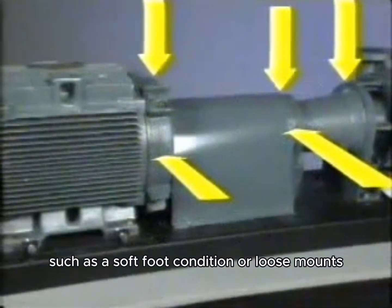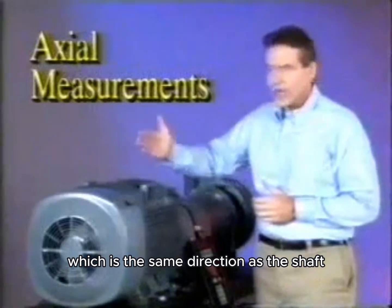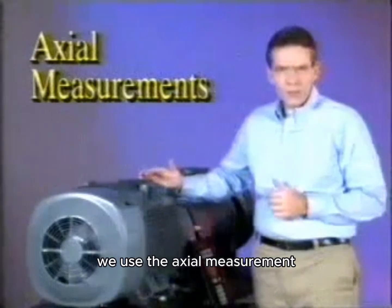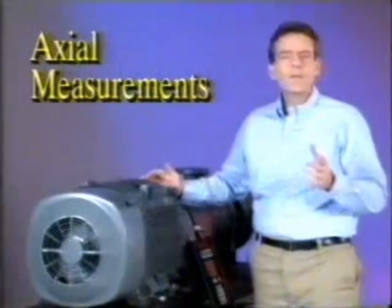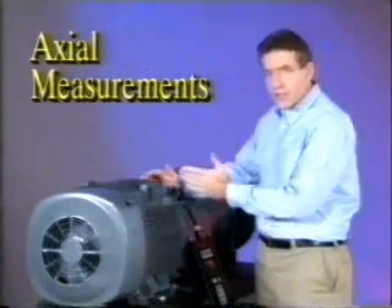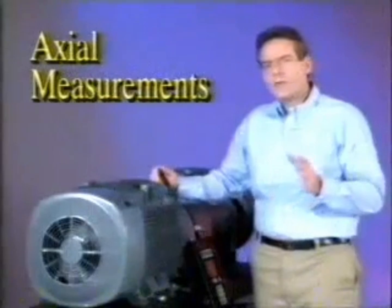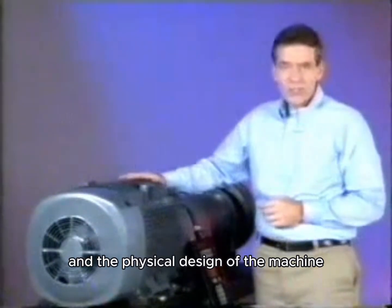An axial reading is one which is the same direction as the shaft or axis. In this motor, the axial measurement could be made at either end. We use the axial measurement to indicate how much the shaft is moving from end to end. Theoretically, the readings at one end should be the same as the other, since the same shaft extends the length of the motor. Actually, the readings will vary some from end to end, due to possible differences in mounting positions and the physical design of the machine.